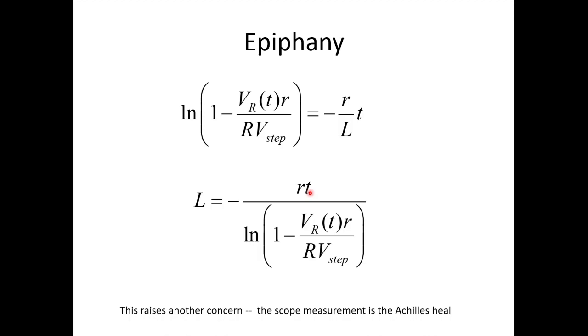Okay, the Achilles heel of this entire measurement is our scope. This will be our scope measurements right here, and they're only from an 8-bit scope. Because in theory, if we could get a better than 50 parts per million measurement here, we would get well below, and this would reconcile and converge very quickly. But because our scope only has 8-bit measurement precision or accuracy, that's our Achilles heel. Since that's going to be the limiting factor, let's see what it's going to do.